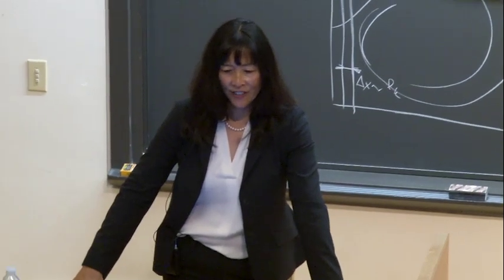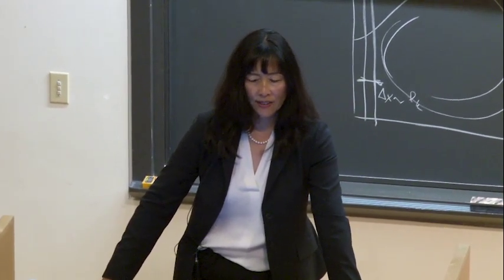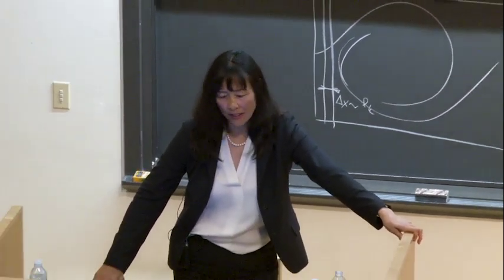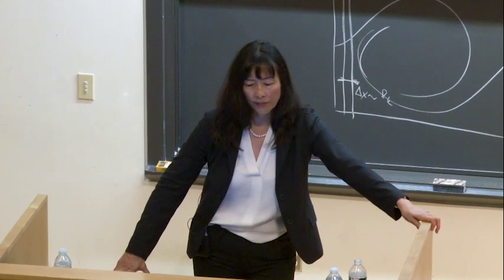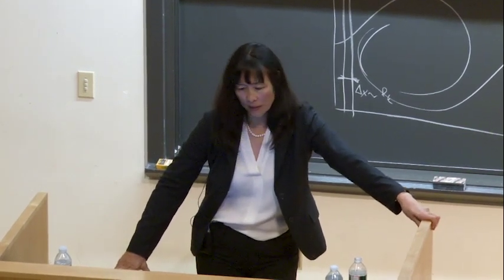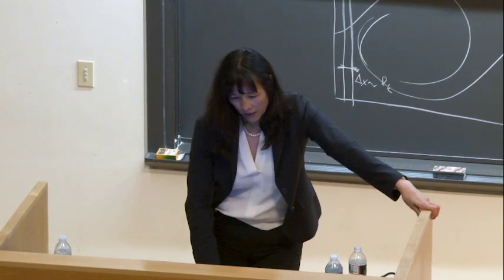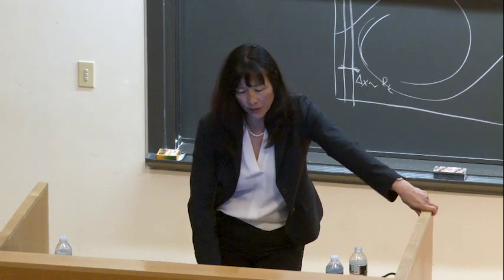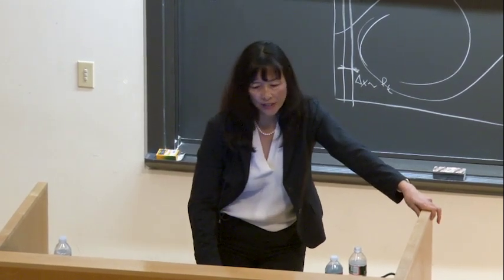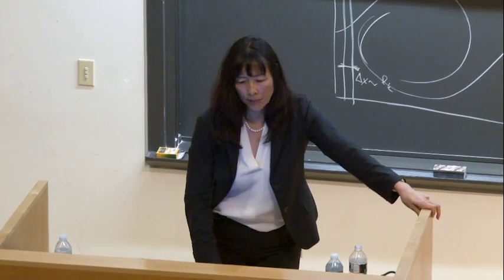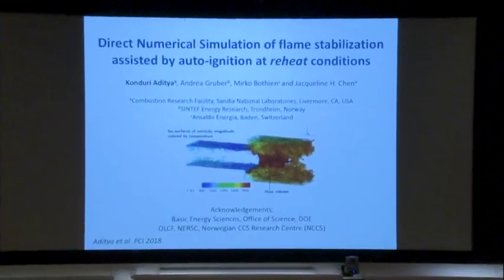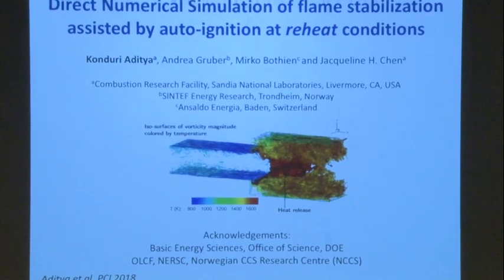I'd like to switch gears now and talk a little bit about DNS of a different application, and that is reheat combustion relevant to load and fuel flexible gas turbines for electricity production. So in this set of DNS that was performed by Aditya Kanduri, my previous postdoc who's moved on to the Indian Institute of Science in Bangalore as a professor, he simulated DNS using a multi-block code built on top of S3D.